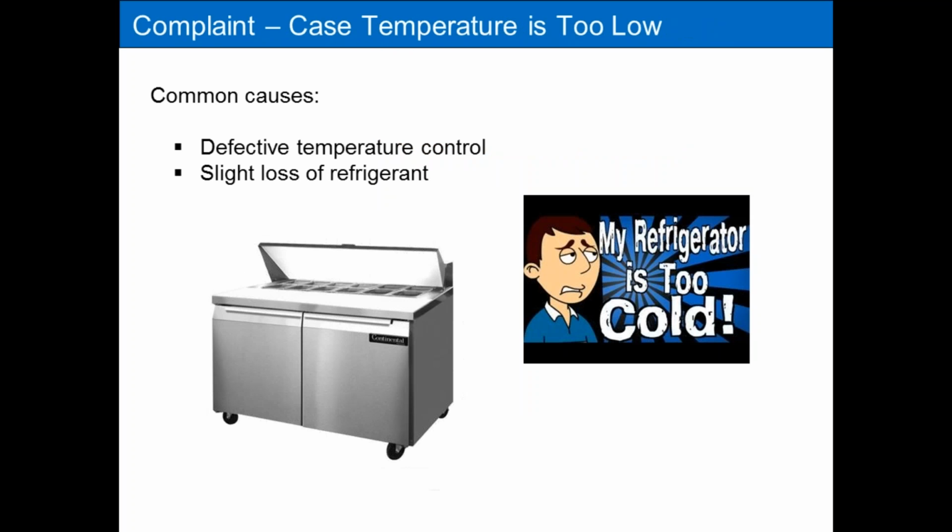So before we get into particulars, there is another possible reason for you to be out there, and that is not as common an issue, but it's possible where the case is just too cold. For whatever reason, the case is too cold, and that's pretty common on salad coolers, produce coolers. They may complain of the tomatoes freezing or the lettuce freezing, and those problems are usually the result of a defective temperature control, a problem with the temperature control, or the temperature control being set too low.